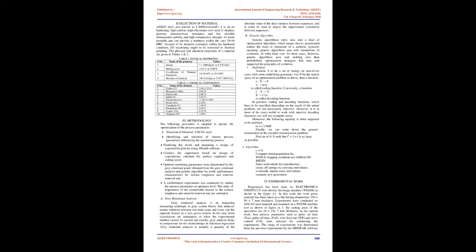In this paper, an attempt is made to investigate the influence of WEDM process parameters on the performance measures of surface finish and cutting speed while machining AISI D3 steel with 3 levels of process parameters: pulse on time, pulse off time, wire feed and servo control.